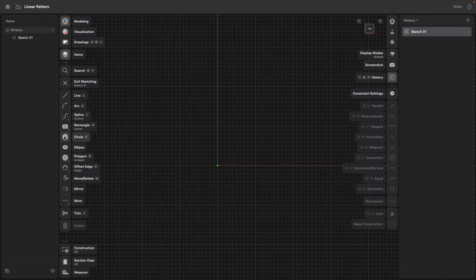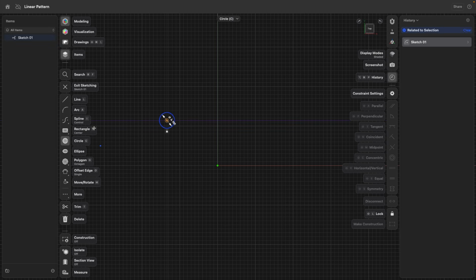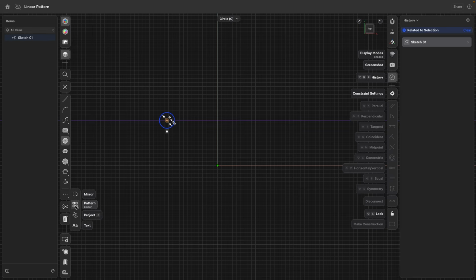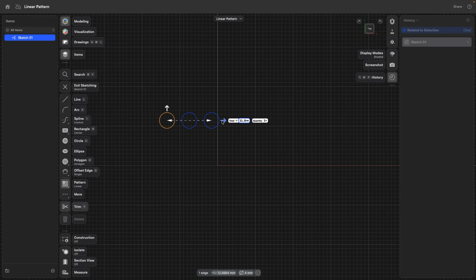And we are creating a pattern one more time. Somewhere here, 4 millimeters. There we are. Then we call the pattern command. Drag this one out, drag this one out. So you see now how we can create a pattern that not only goes one direction, but fills a square area. This is now an interesting area where we also can introduce how to add variables.